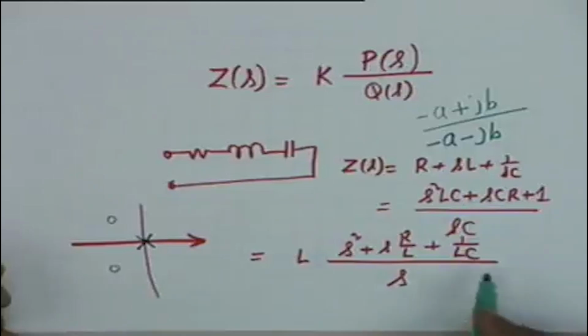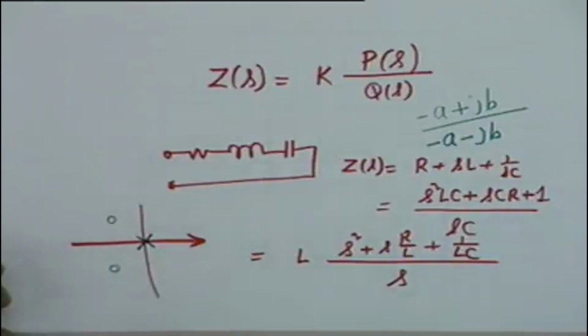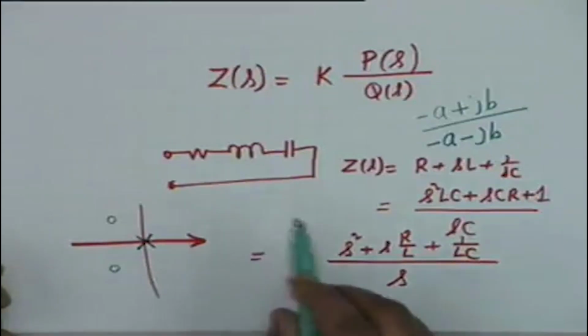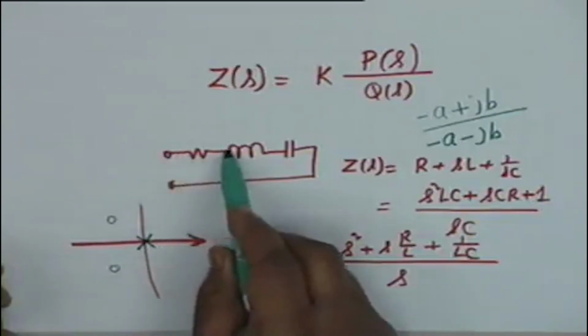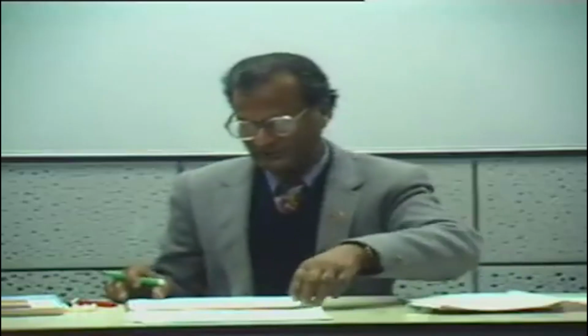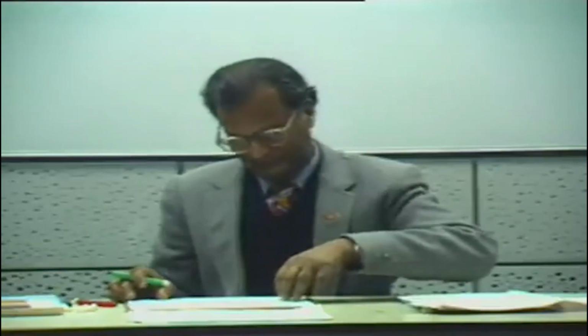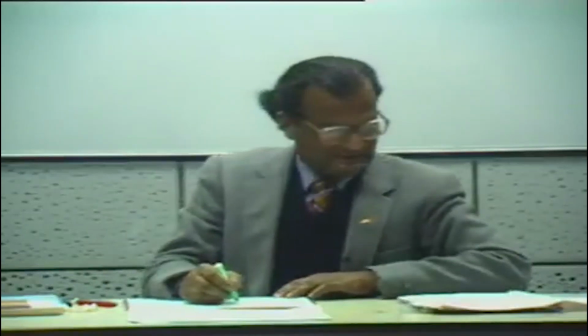All right. Then the two zeros here may be complex, may be real and negative. And at a zero, the function becomes 0, which means that the total circuit acts as a short circuit for that particular value of s, not for any other value of s. We are going to take another example. Let's take that example. Before we generalize this, let's take an example.